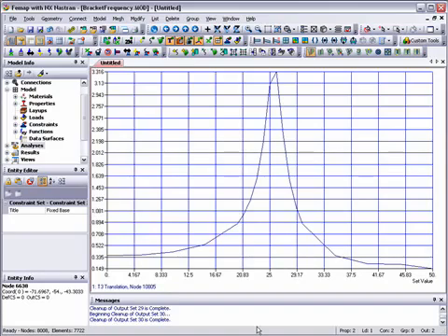You can see that close to the first natural frequency at 26 Hz, there's a displacement of 3.312 mm, showing a dynamic magnification factor of almost 10 over the static response. The static response is visible at the left at 0 Hz. A more refined frequency sweep would probably reveal an even higher displacement value.